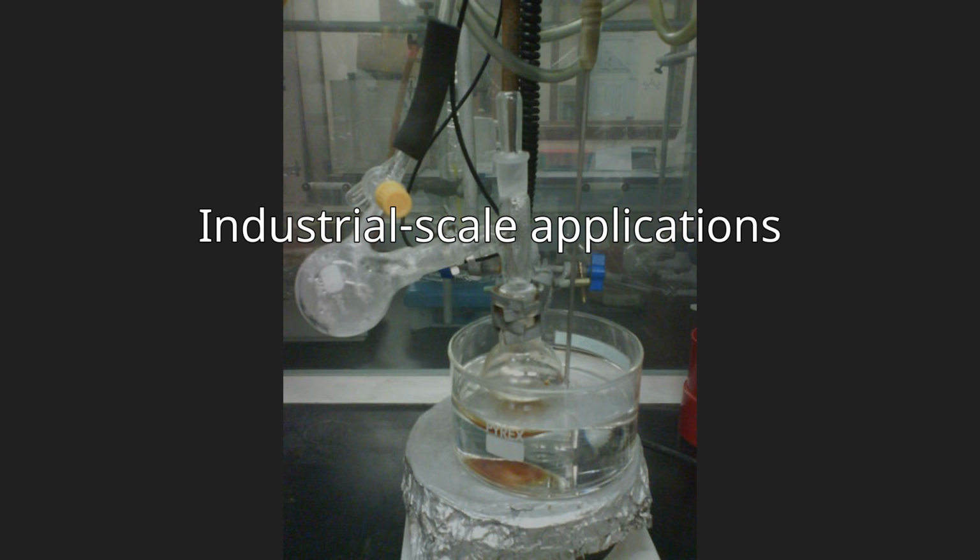Vacuum distillation can improve a separation by prevention of product degradation or polymer formation because of reduced pressure leading to lower tower bottoms temperatures. Reduction of product degradation or polymer formation because of reduced mean residence time, especially in columns using packing rather than trays. Increasing capacity, yield, and purity.